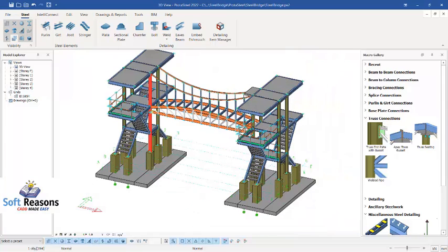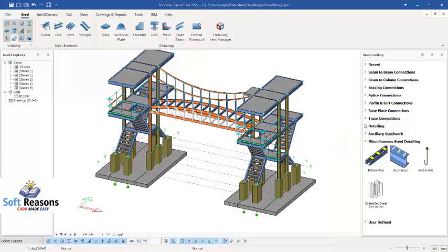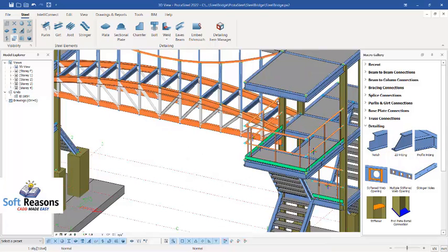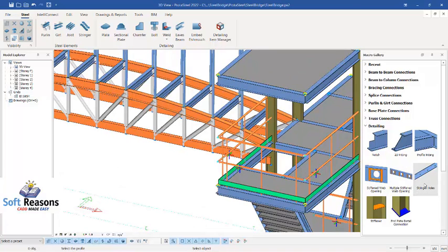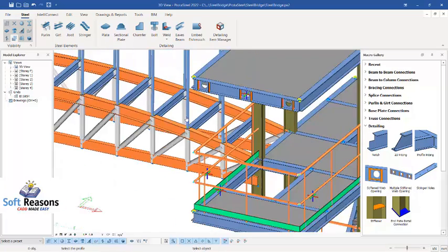All right, so if you want to have castellated steel members, you will have to come to the detailing tab, these provisions, detailing. So for the castellated, you will just have to click on this. It all depends whether you want the castellated with stiffener. So you can see the multiple stiffened web opening. We can select right there to create that successfully, as you can see.